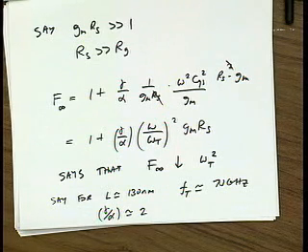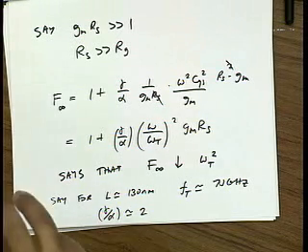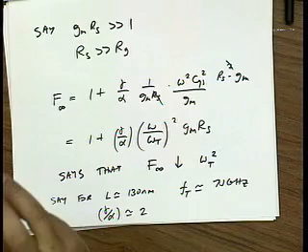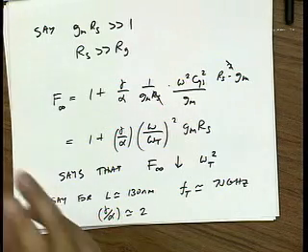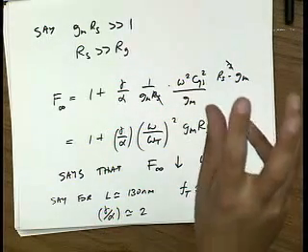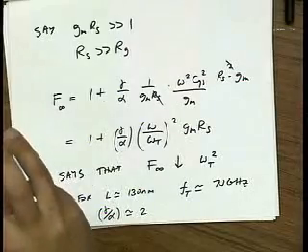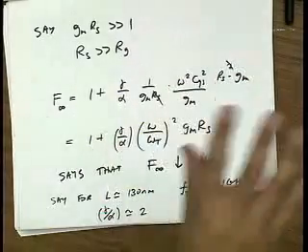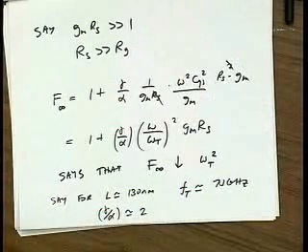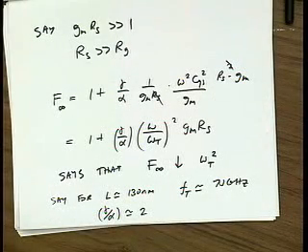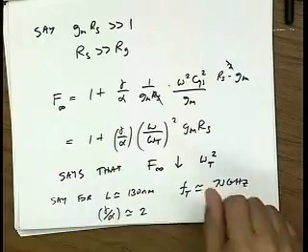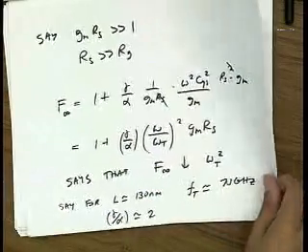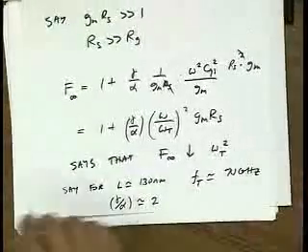So a nice way to do the calculations and not have to worry about this correlation is just to assume that the gate resistance is independent from the channel resistance. Now of course the channel component is the one that's correlated, and the gate resistance component is completely uncorrelated, right? That's a physical resistor. But you get a pretty good result if you ignore that correlation. Okay, any questions?